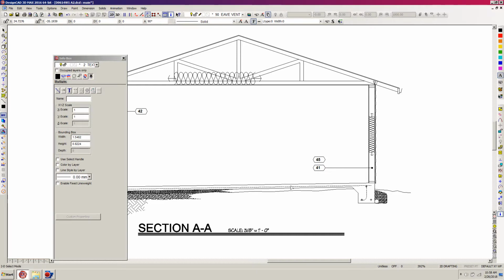So I'm going to use the arrow command, greater than, and hit H for orthogonal mode, so I'm coming out straight. And then I'm going to set a point. I'm hitting H again to toggle off orthogonal mode, so I can do a slopey arrow here. And K, pointing to the slab. So there's my arrow there. Now I'm going to hit Control W.